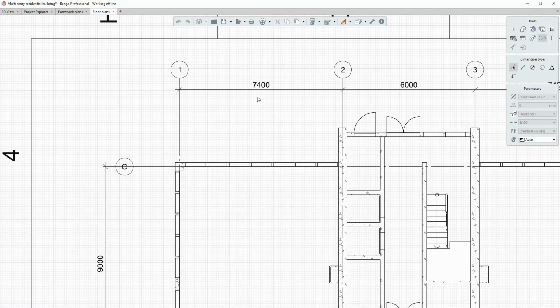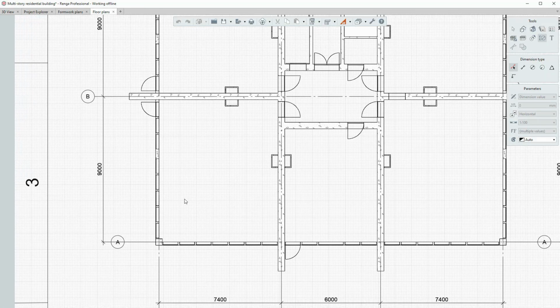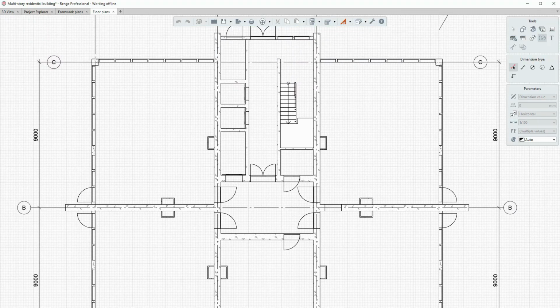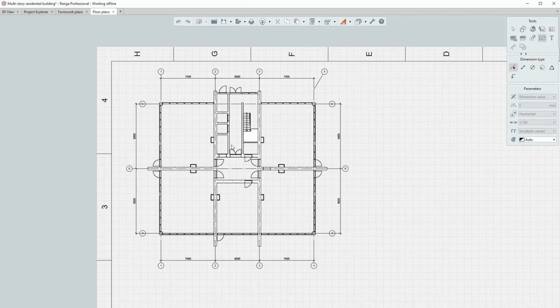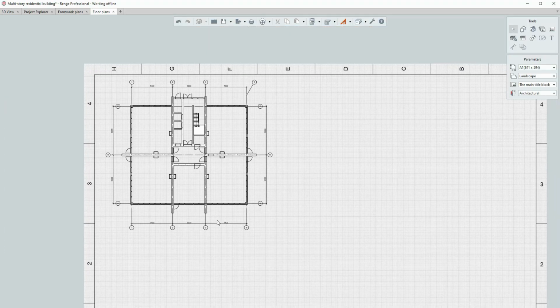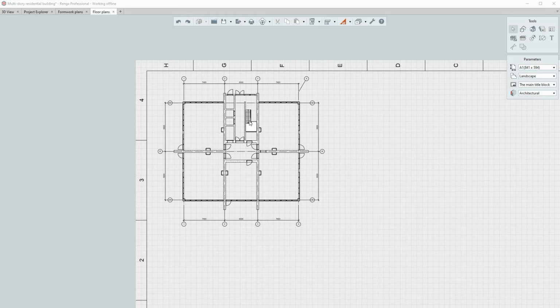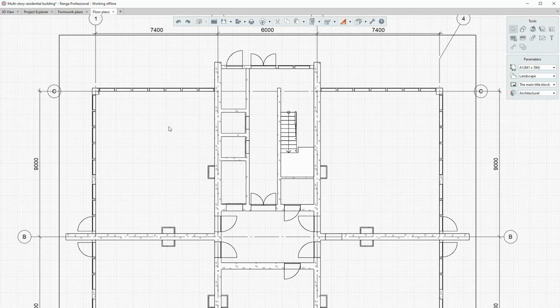If the dimensions are plotted on the view, linear dimensions and elevation marks will update automatically when the model is changed, but only if they were built using object snaps, the object endpoint. Diameter, radial and angular dimensions are not updated. We recommend you check the dimensions on the drawings after the model is changed. Users can also manually finalize the drawing and add dimensions that were not included in the model.